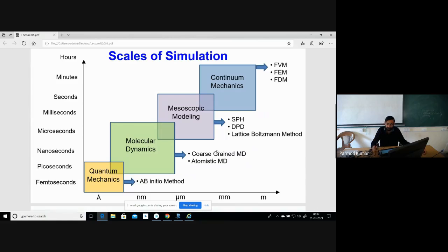Okay. So when we study the basics of fluid dynamics, we have studied the concept of continuum. In terms of continuum, we have a non-dimensional parameter called the Knudsen number. If the value of the Knudsen number is very small, less than 0.01, then only we consider the assumption of continuum.